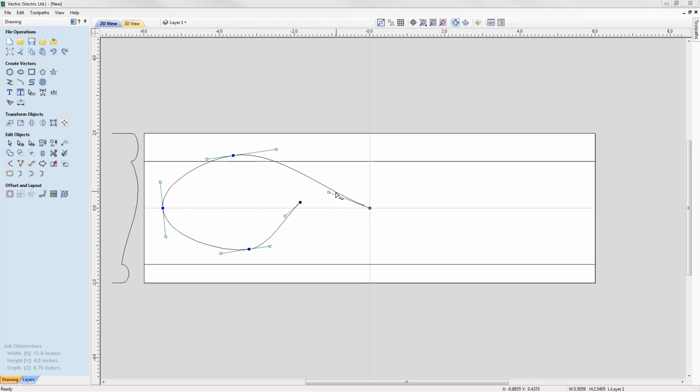So we're going to start over here. Now I'm going to take this control handle here, and I'm going to move that over to the right hand side. And the reason for this is that when we come to model this stalk, I'm ultimately going to model one portion, we're going to mirror and flip it so that it creates a copy on the other side. So having this control handle over to the right just means that we're going to transition through x0, y0 seamlessly to when we mirror the part on the other side. So you won't be able to tell it was created from two parts.